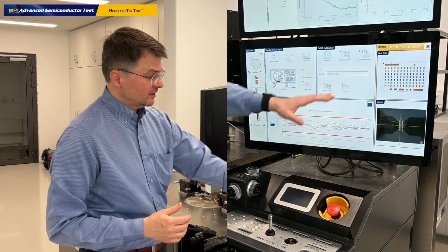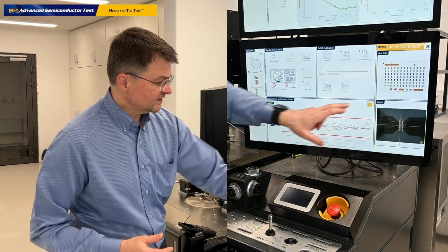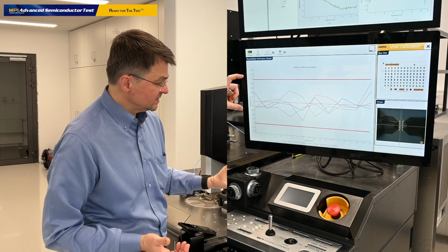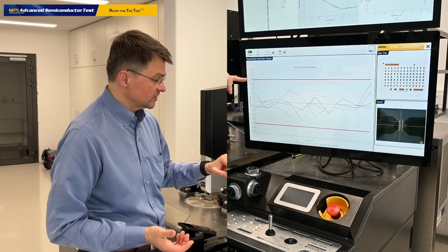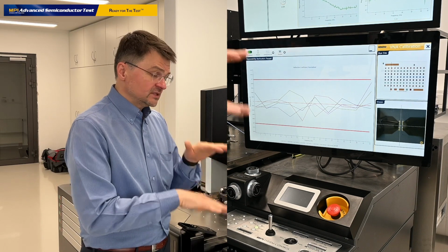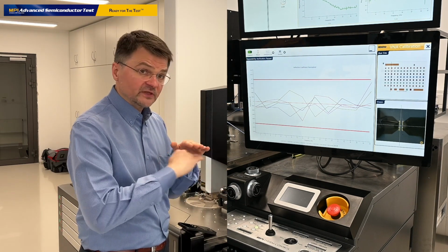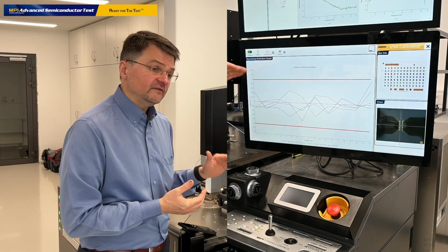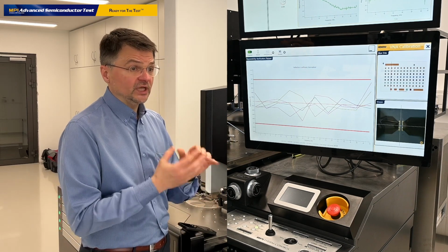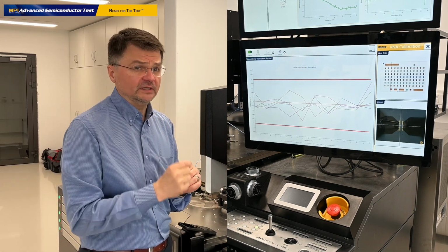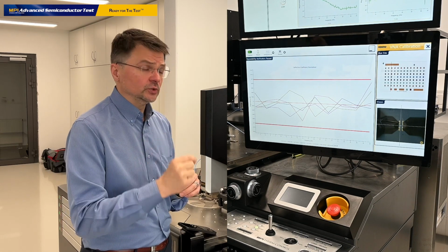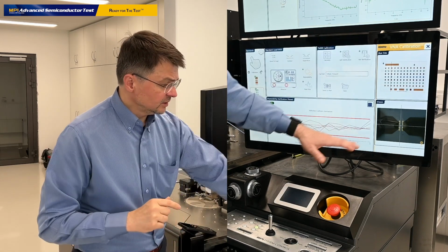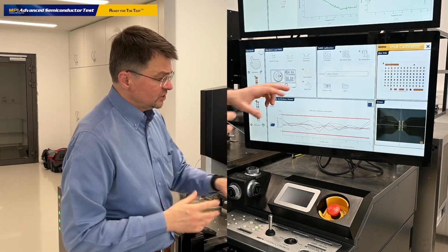So one more time. From the widget that controls the measurements, we have access to the repeatability of the data. Imagine here we set up pretty tough boundaries for the repeatability pass-fail criteria. This is 0.01 dB. It's the measurement deviations from the reference measurement, the first sweep, and all other sweeps that we measured on the particular standard. And keep in mind that the deviations are relatively big because we look into very small differences of very, very small numbers. When we measure uncalibrated data on the load, usually we operate with quantities which are extremely small. And they're still within the predefined boundaries, which is a good sign.